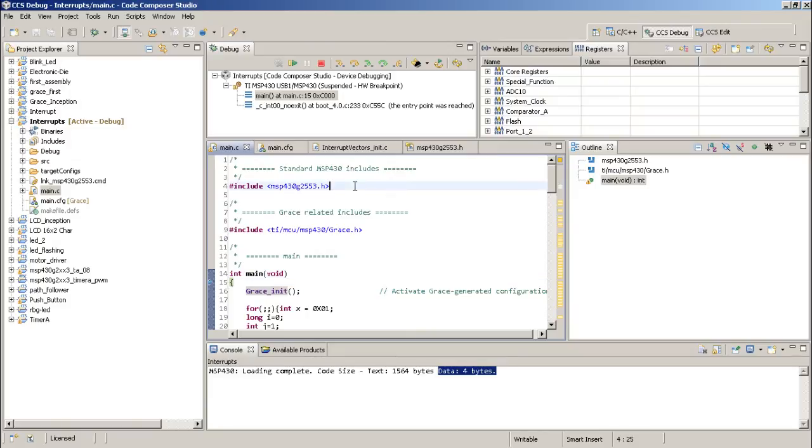If you have any doubts regarding hardware interrupts, how to give an interrupt, switch debouncing, yes, switch debouncing. When you press a mechanical switch, due to the mechanical action there is a recoil. The switch will have a spring-like action. It will move up and down.